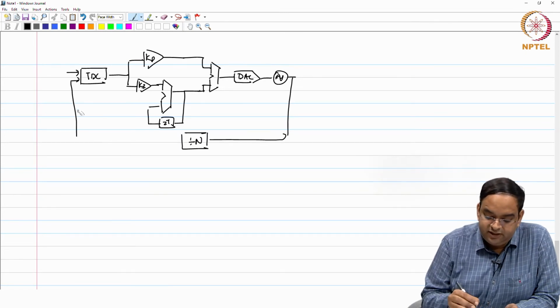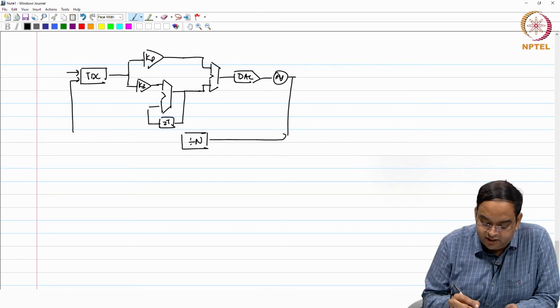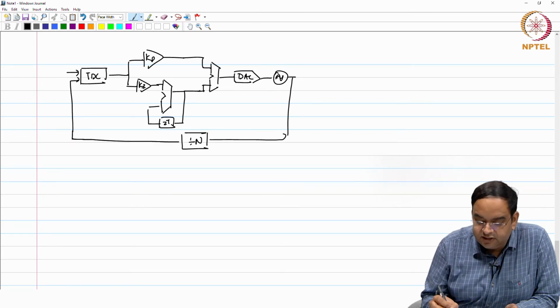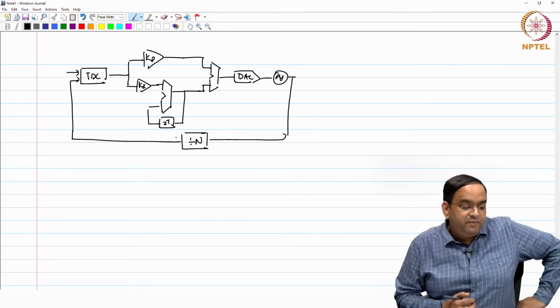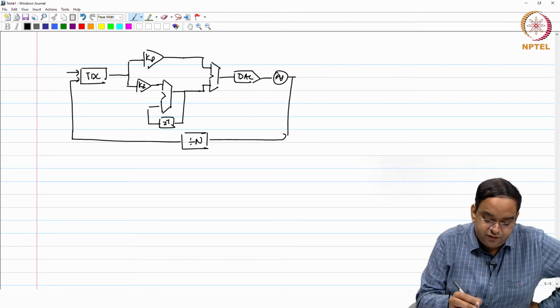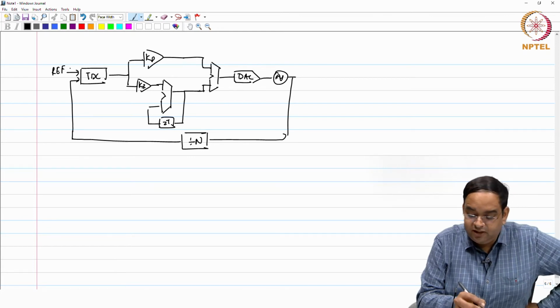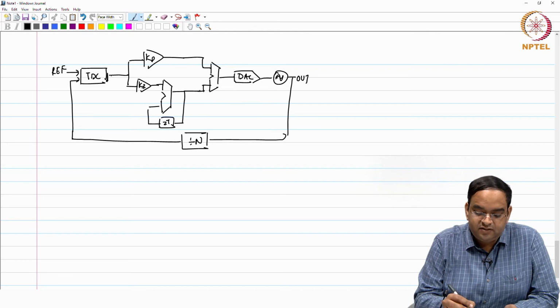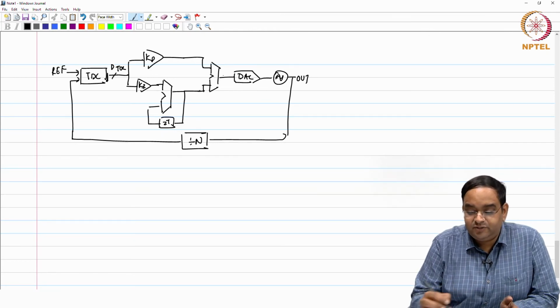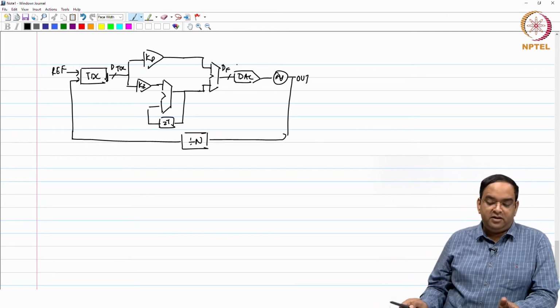So, in this case, this is the basic digital PLL, just replacing all the blocks by their digital equivalent, which gives us bits like 1 or 0. So, here we had the reference clock, we have output clock here, right. The output of the TDC is digital bits DTDC, and everything is in terms of bits here till this point, which is the control word for your DAC.